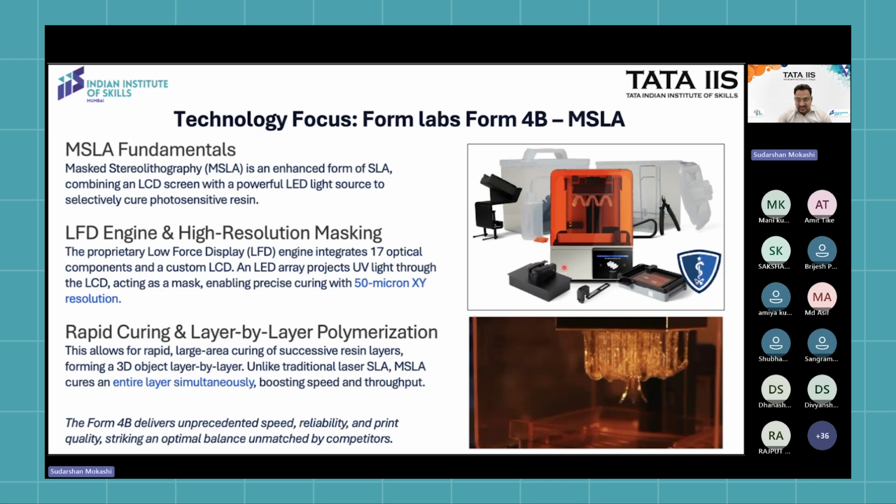So in the image you see this is the build plate, and this is the tank where we can add the resin. This is our recoater to move the resin layer by layer, and the build plate goes from bottom to top. So this is the process. This technology is used mostly in the jewelry industry and for dental applications, for parts requiring high accuracy. In this technology we did one case study that I will present in the next slide. So we'll go for that case study.